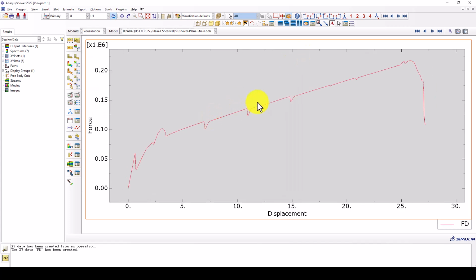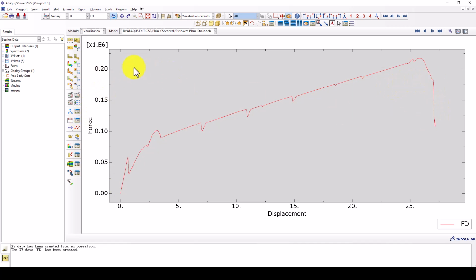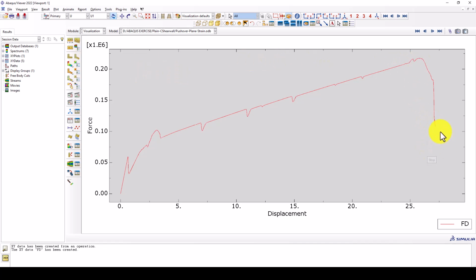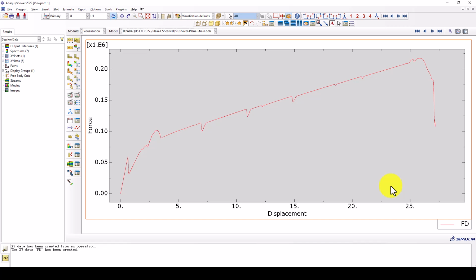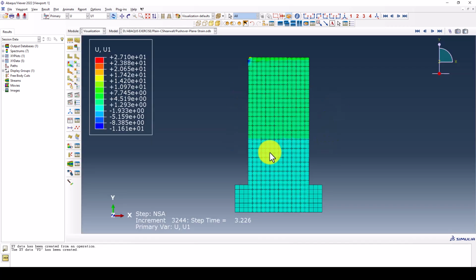And now you can see here is the curve. This is the force displacement curve, and it goes like this and here. So it's almost 250 kilonewton maximum capacity, and the maximum displacement is 25 millimeter, almost about 1% drift. You can manipulate this data, and also you can see some other parameters, such as the peak equivalent plastic strain, these things.